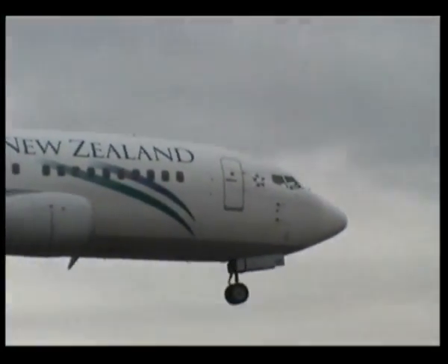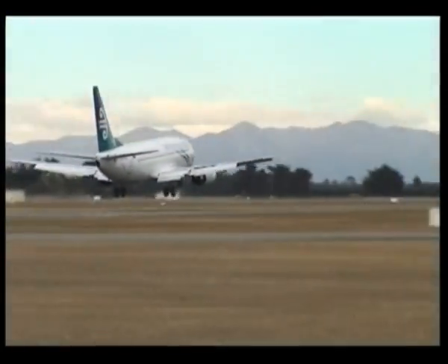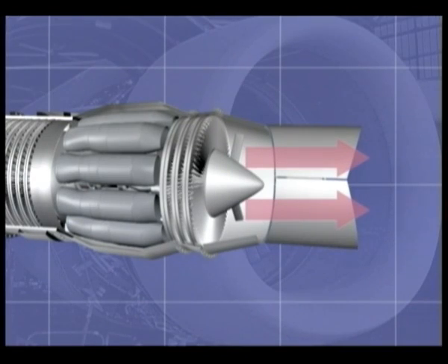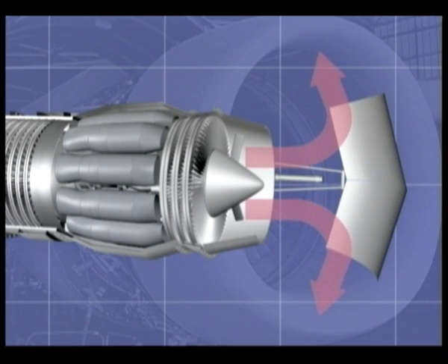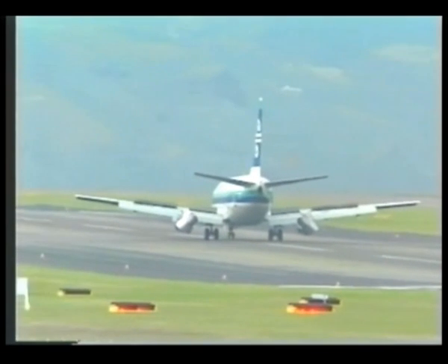Thrust reversal is a means of reducing the landing run of an aircraft without use of wheel brakes or the use of a brake parachute. On a pure jet or turbofan, the only simple way to slow the aircraft down quickly is to redirect the exhaust gas stream, thus using the engine power as a deceleration force.